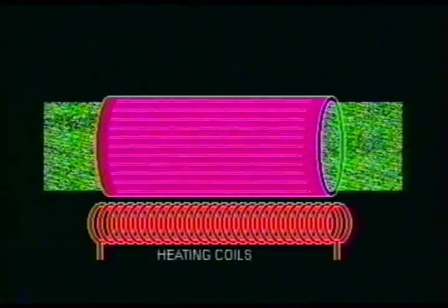Next, the silica cladding tube, or shell, is placed in a special lathe-type machine. Special gases are then passed through the tube, which results in the core material being produced. The tube is brought to a very high temperature as the gases are sent through it. This causes the gases to form deposits inside the cladding tube, which results in the core material being formed.